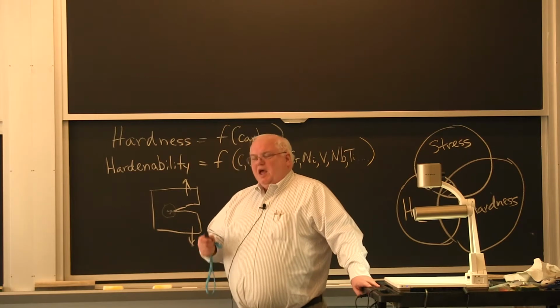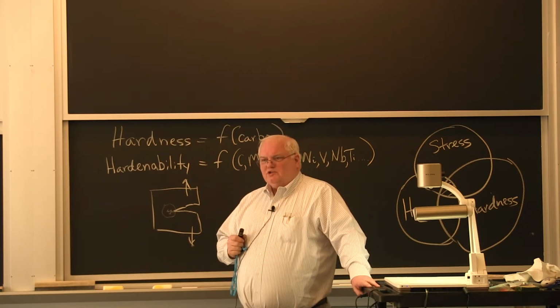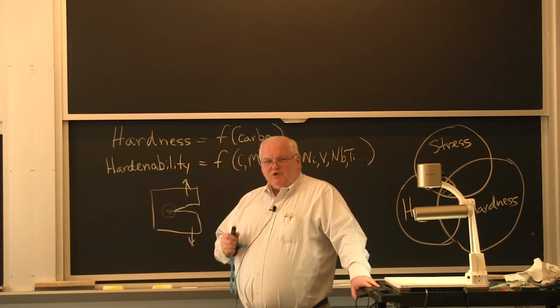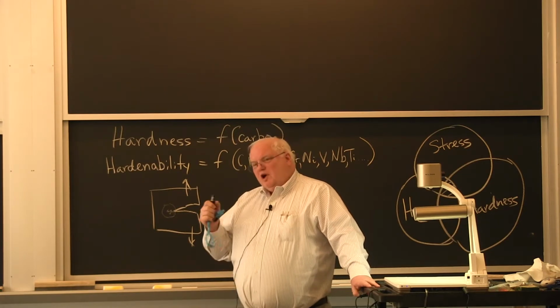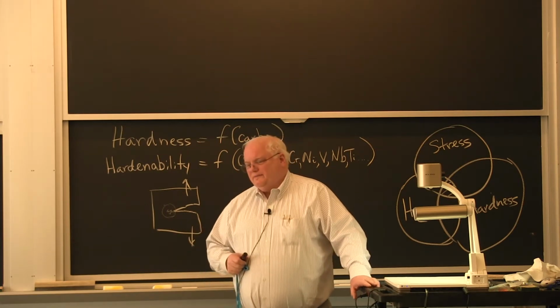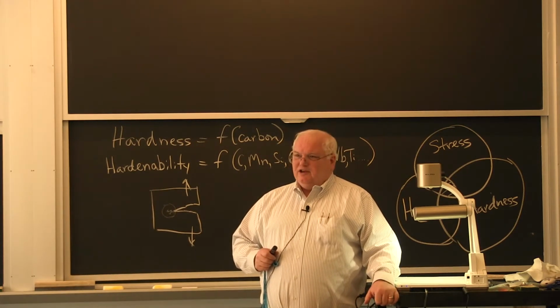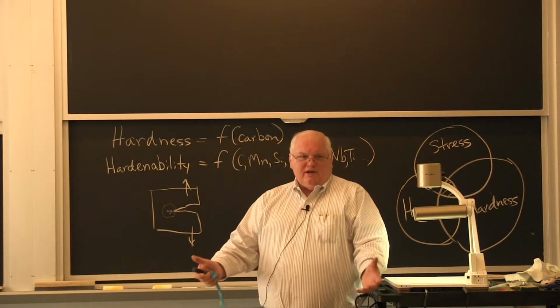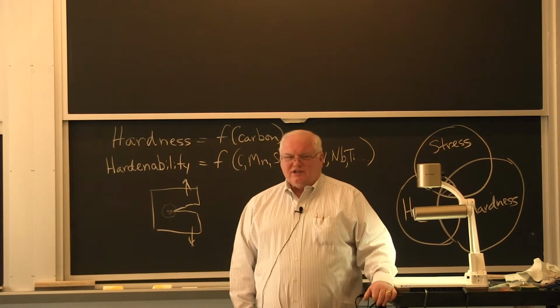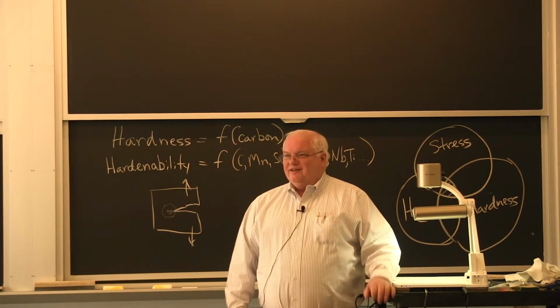So moisture, humidity. According to the U.S. Navy, you're not supposed to weld a nuclear submarine if it's more than 85% relative humidity. Do you know how many days in a shipyard right next to the ocean on the east coast of the United States, which is where we build submarines, either in Newport News or in Groton, Connecticut, it's above 85% relative humidity? About 200 days of the year, right next to the water. It's not too surprising. So do they quit welding for 200 days a year? No. They keep welding, okay?